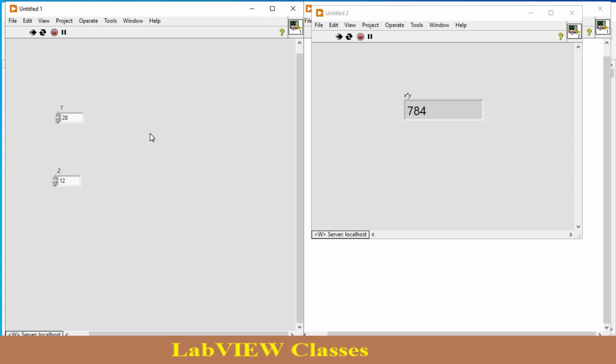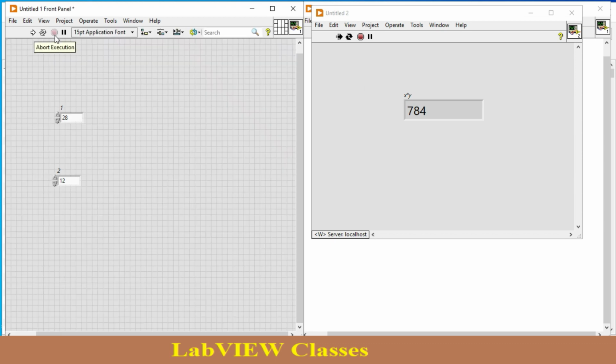You can use it any way, for example, you create a program using your DAQ card. You acquire the signal of pressure and flow in one program. In another program, you acquire voltage and current, and in another program you want to combine all these four. You just go with global variable in that case. So this is the case of global variable.